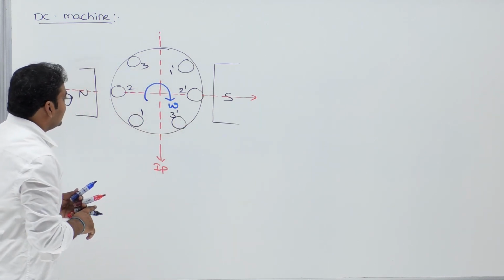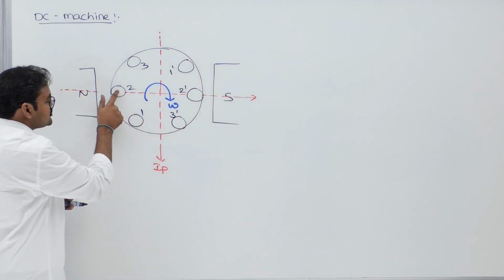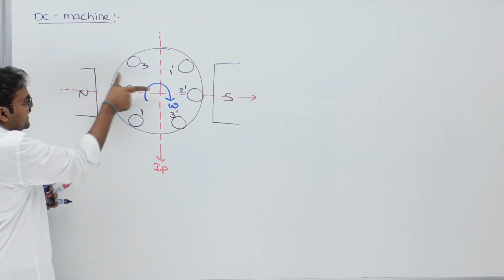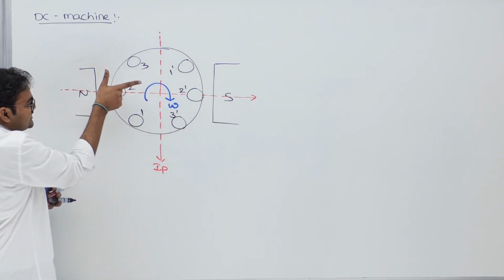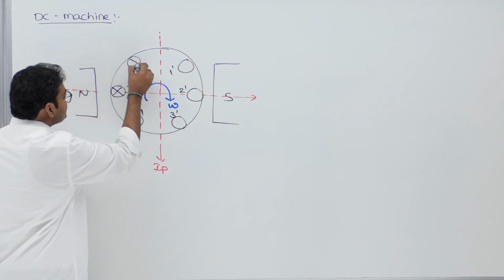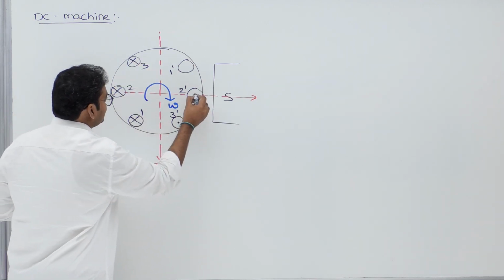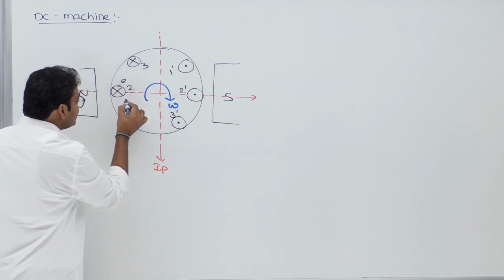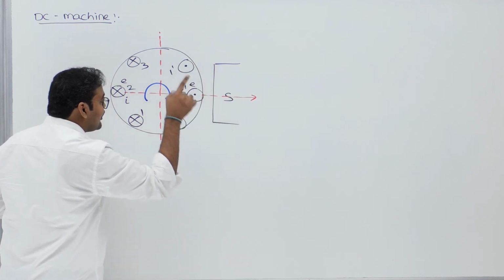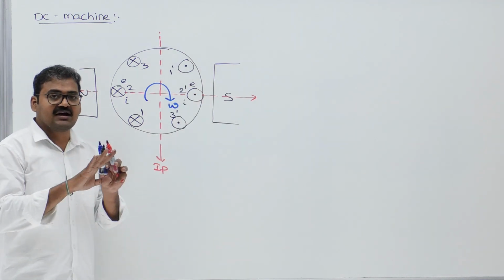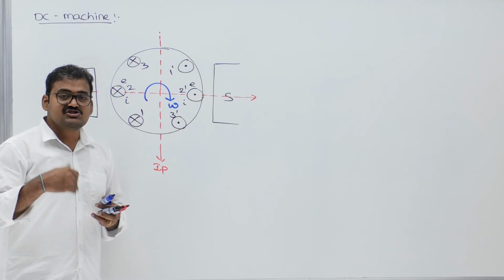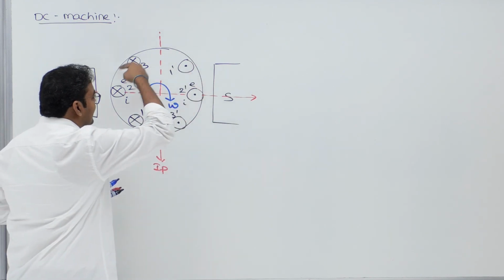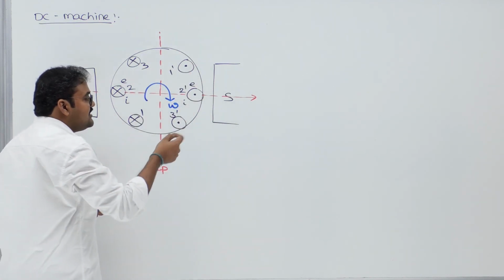Okay. Now tell me, conductors are directly moving this time. So this conductor 2 is moving in upward direction, clockwise. Magnetic field is from north pole to south pole. My central finger will show the polarity which is into the plane. Under south pole, the polarity will be out of the plane. The moment when EMF is induced, immediately current will circulate in case if a load is connected. If load is not connected, current cannot circulate. Assume the load is connected, current started to circulate. Therefore, these rotor conductors are now normal conductors or current carrying conductors.